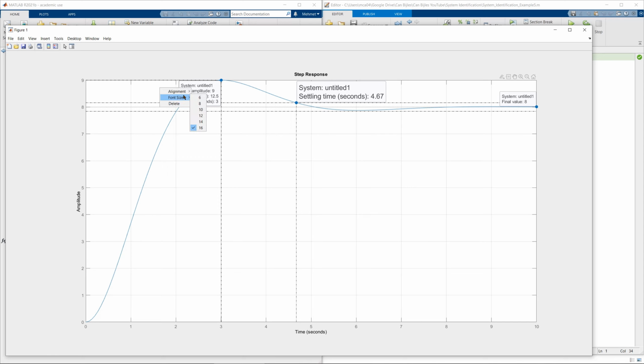Also make this a little bit larger. And of course we can look at the 5.8 exactly, so what's actually going on there. So if I go there at 5.8, I can see it is 7.88, and we had actually here 7.84, so it's also very close to what we have from our plot. So this is again a confirmation of our transfer function of our system. So that's what we have from the plot of the step response.